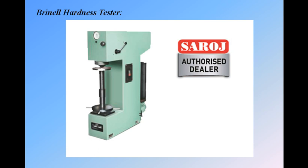So in the Brinell hardness tester we put a high load on a specimen, so that specimen must have high thickness with optimum hardness, because a specimen with high hardness and low thickness may crack when we apply the load, and that cannot give you the proper hardness value. To get a proper hardness value, this Brinell hardness tester can be used for those specimens which have good thickness and optimum hardness. Okay, next, and this is what we have seen. In our lab we have the same equipment, Saroj made equipment, which was given to us by FI Industries.